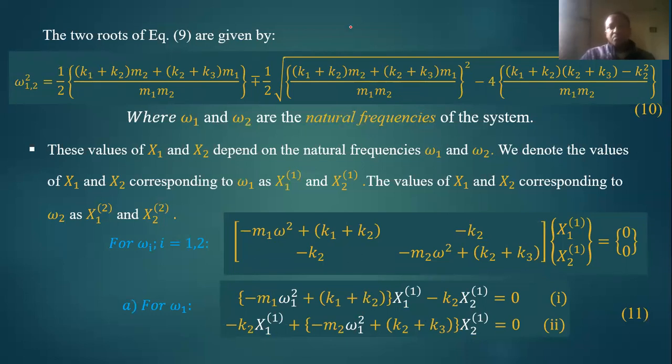As we know, x equals minus b plus or minus the square root of b squared minus 4ac, all over 2a, is our quadratic formula. So our x is in squared form now. So x1 and x2 are given by this equation. From that, we can obtain omega 1 and omega 2, which are the natural frequencies of the system.